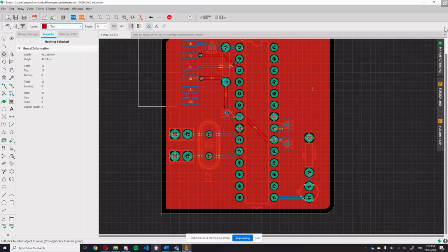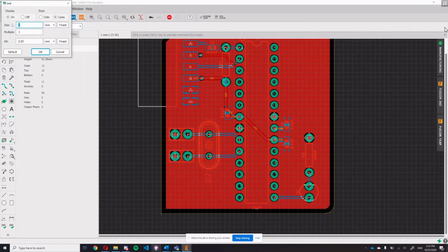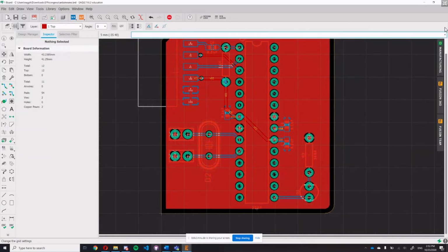Now this is pretty optimal, but in some cases the power needs to go around the board, some distance on one side and some distance on the other side. But also the fact itself that you have these layers not connected creates some problems. So we are going to resolve that by adding some vias.